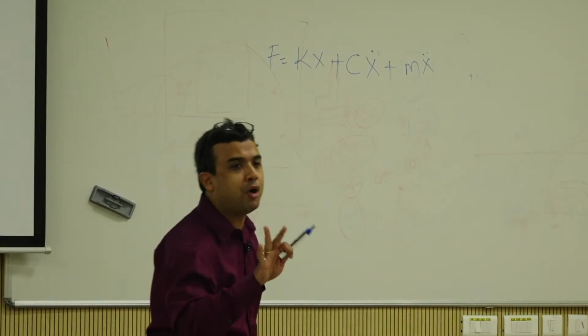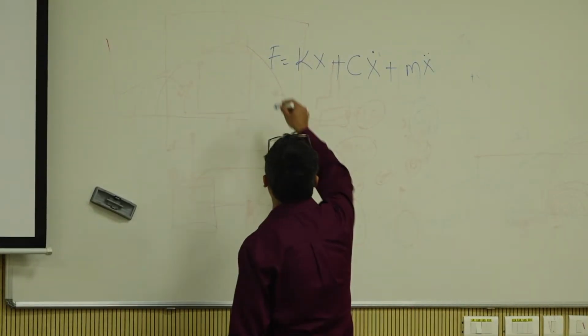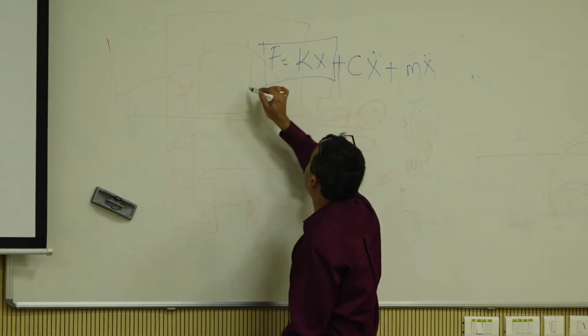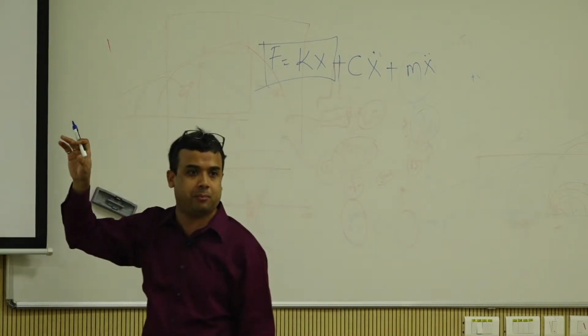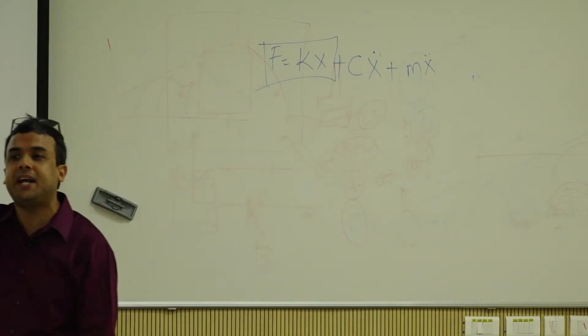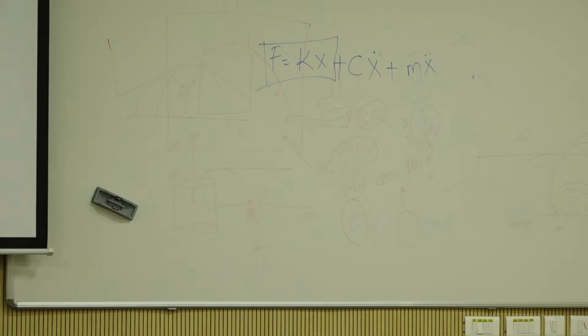In resilient modulus testing, whenever we go into that, you will see we are kind of still simplifying it only to the first term. It is a repeated loading test, but we are not doing a true dynamic characterization. So it's not a dynamic property.